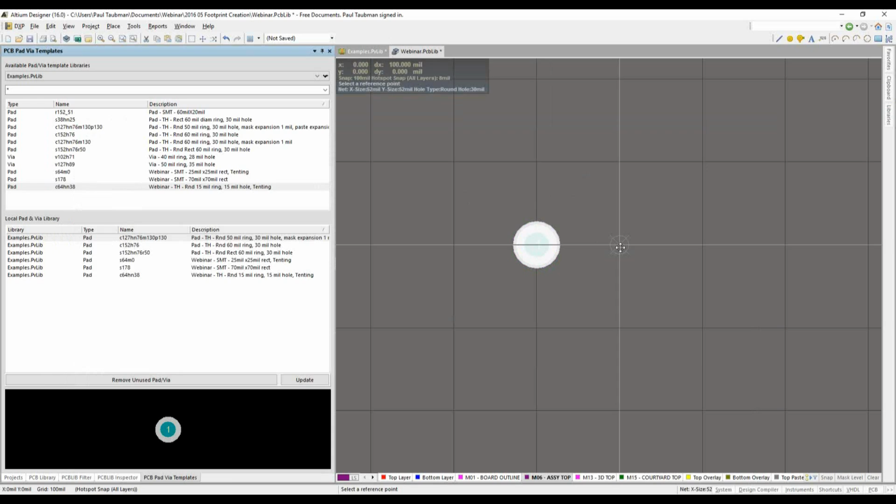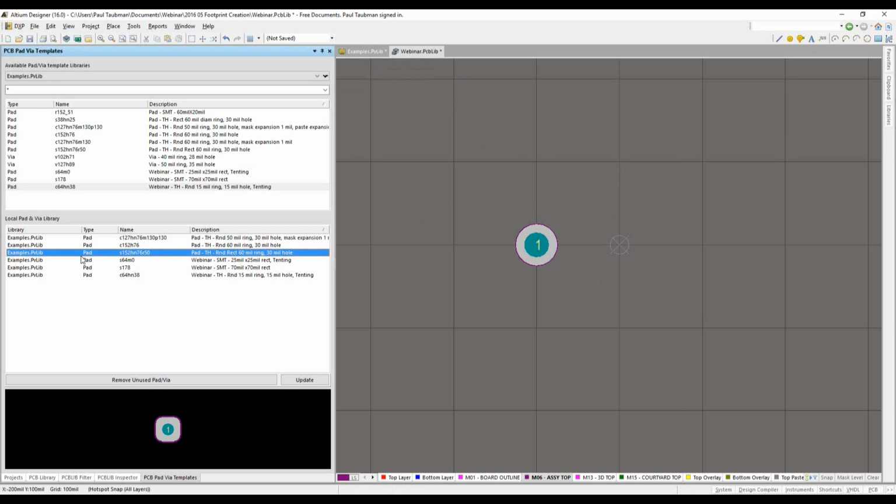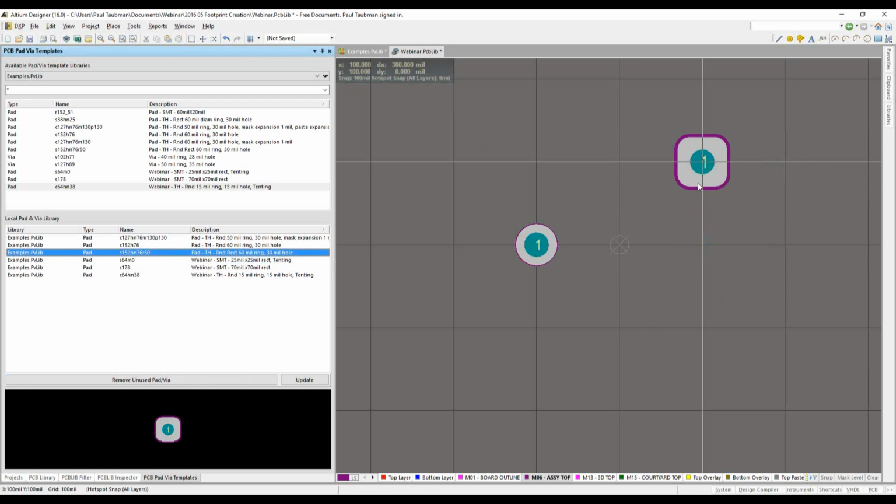So I'm going to do that right here, and it becomes very powerful because, again, of the concept of symmetry. And because I have this over here, I can now paste these each in at a different angle. Rather than trying to figure it out, I can just have it go along in 45. Now, by default, if I select something, I'll drop it down over here. Let me place it just for a moment. When it's on my cursor here, I can hit my space bar, not that you're really going to see it because this is symmetrical, and it will actually go around. You'll notice that it's going at 45 because I set it up at 45, but if I've got it on my cursor and I'm moving it around, I can hit my space bar and do the rotation.